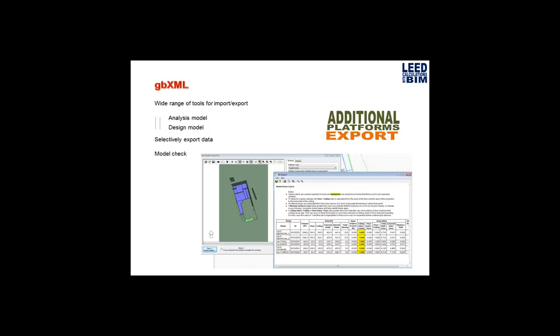that you're going to be using to analyze. And I think this is really critical, because if the data going in is faulty, then the results of your analysis are going to be faulty as well. It's just inevitable. And there's no sense in wasting time running an analysis on faulty data. That's why I suggest you have a separate model, just to have a clean export. Because if you're exporting out junk or things that are not going to be translated with the schema, then your analysis results are just going to be faulty.